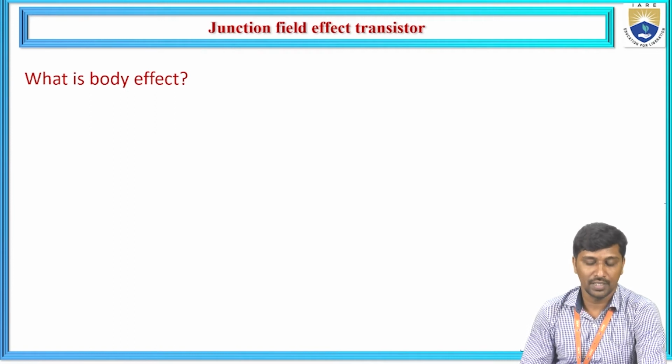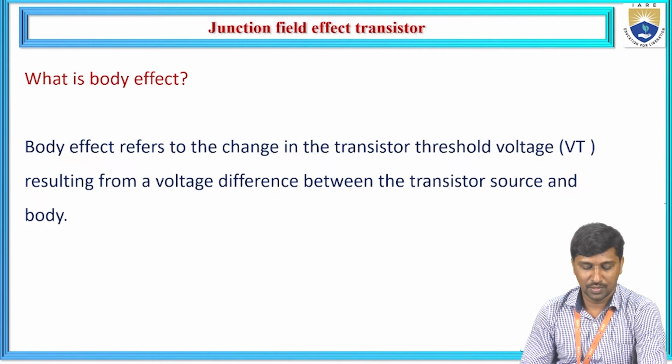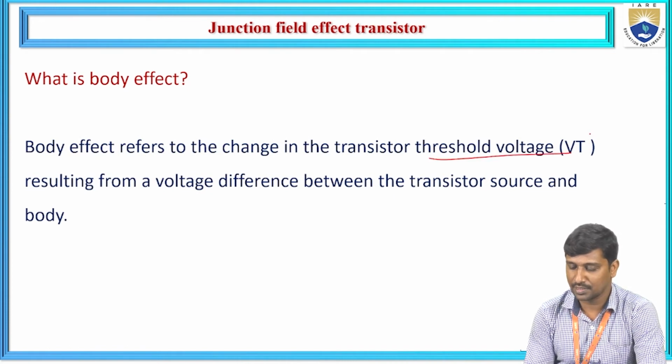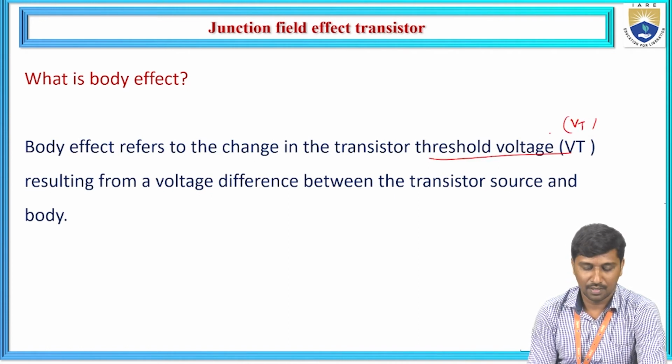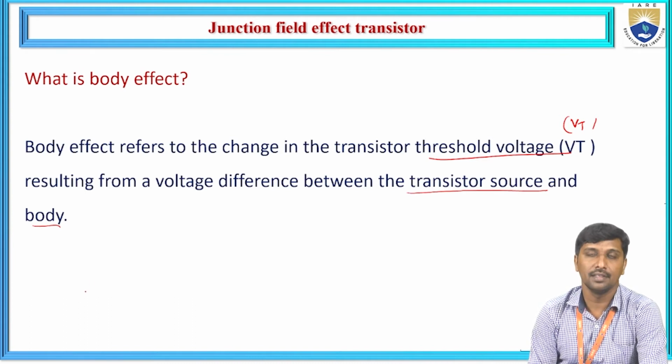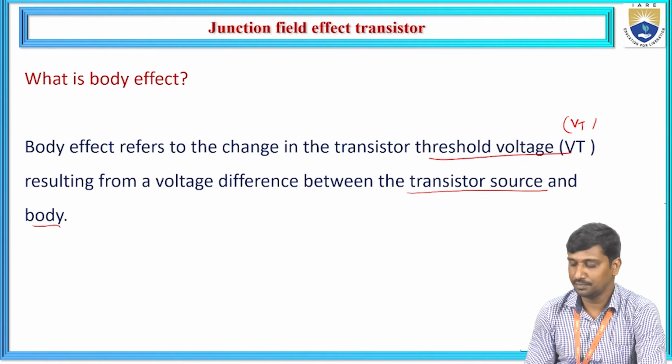Now, what is the body effect? The body effect refers to the change in the transistor threshold voltage, that is VT, resulting from the voltage difference between the transistor source and body. This statement defines the body effect of the field effect transistor.